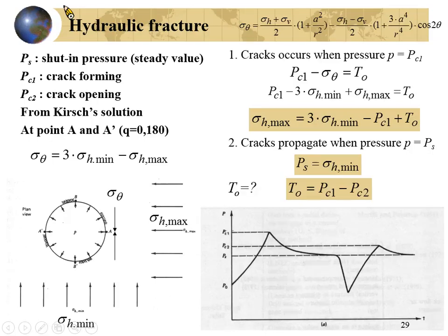Because this kind of crack or damage is related to the compressive stress. We don't try to increase the pore pressure in this segment. The fracture is due to the principal stress itself. The fracture of this one is because of the large pressure inside the borehole.